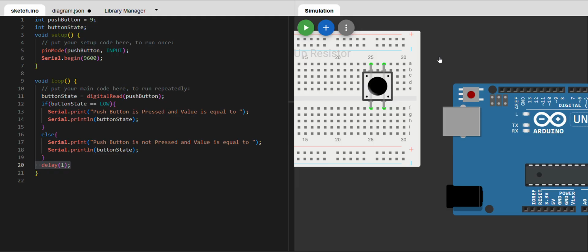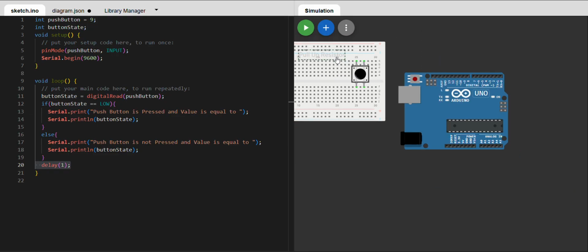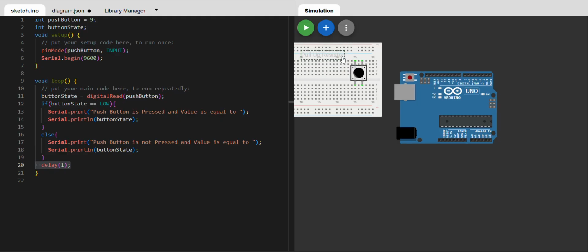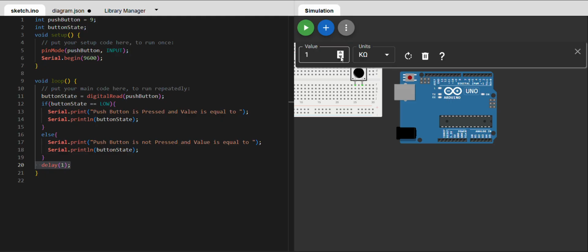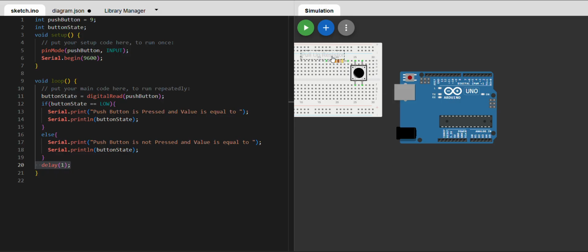Just a second. I'm going to discuss the push button in active low with pull up resistor. Let us discuss the push button in active high with pull down resistor in the next class. For that I have taken a resistor. I'm going to keep its value at 330 ohms. There is no particular reason, I'm just keeping it. In the previous class we also used 330 ohms. Its name is pull up resistor.